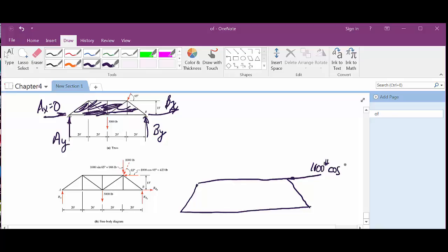cosine of 65 degrees. And then I've got 1,000 pounds sine of 65 degrees. So I just broke that out into the components. See, now after that first chapter, this is just a piece of cake, right? Somebody say yes. Yep. Make me at least feel better. Okay? Somebody's getting it. This part of it hopefully is starting to make some sense to you. As long as your angle is coming from the x-axis, you do that. Keep it in that 90-degree quadrant.